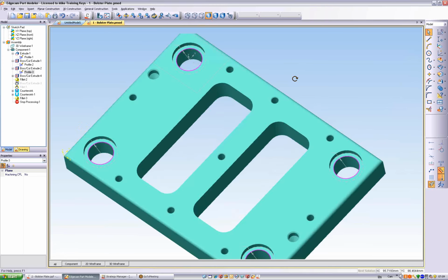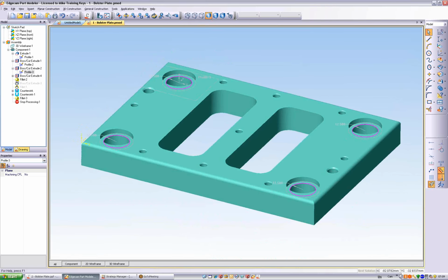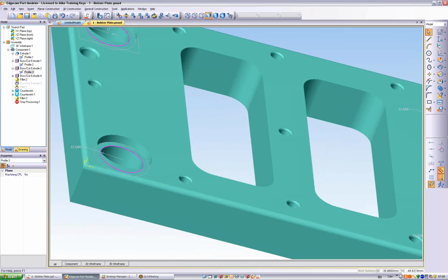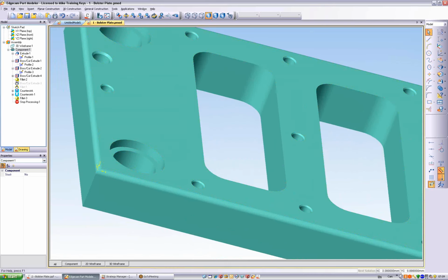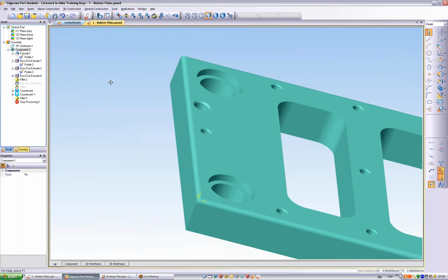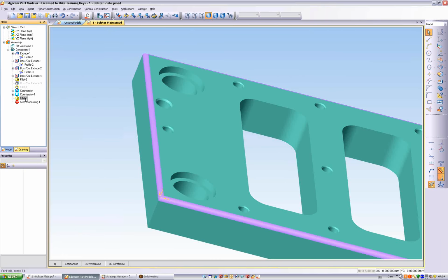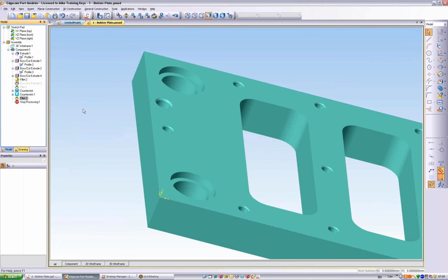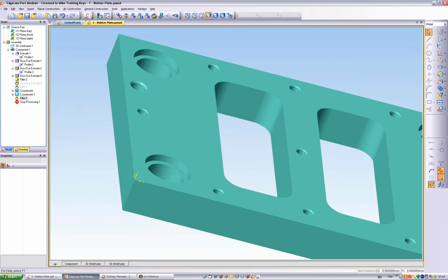Obviously this could be a variable fillet, in this case a standard fillet. And then what we're obviously seeing here is the fact that we have that fillet perfectly formed. If we don't want the fillet, we can just suppress it, so we're not actually going to delete it. It means suppressing, very useful for machinist people who actually want the feature on the model but don't want it to be machined. We can take them away by suppressing, or indeed we can just delete the feature.